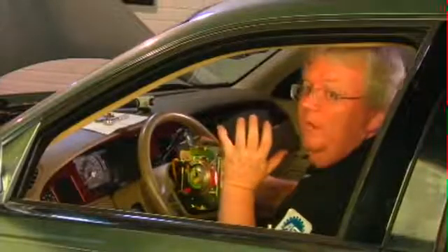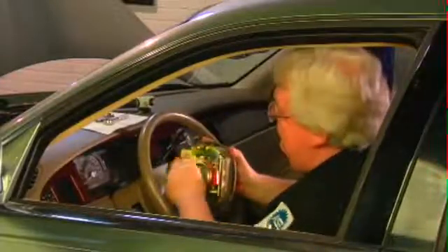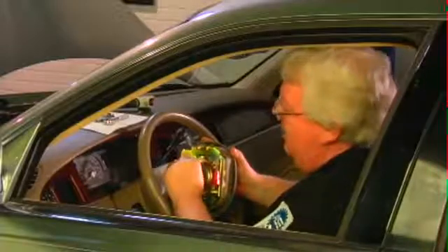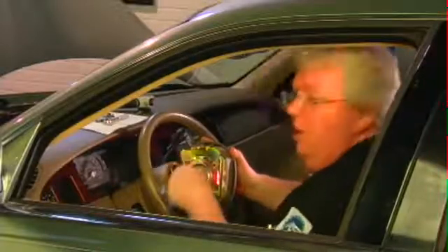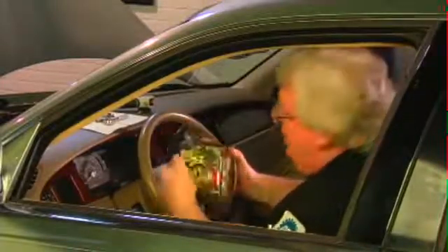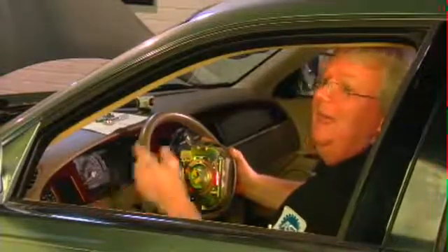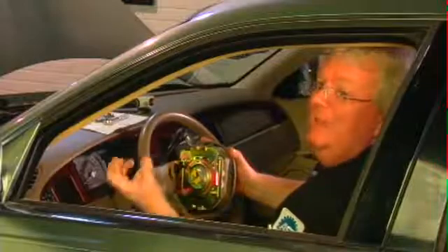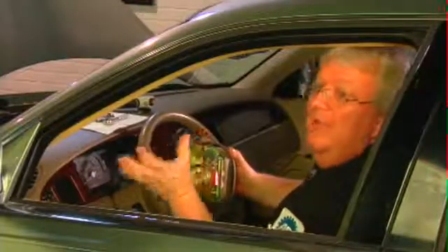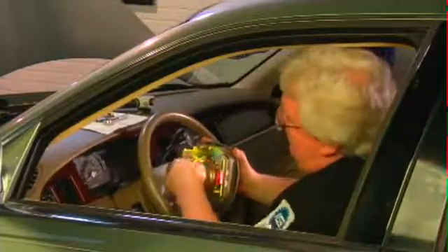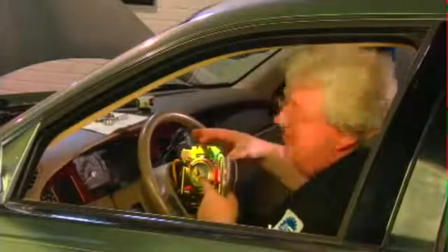Now, since we have disconnected the battery and waited a minute, even if there were shorted wires down lower in the harness getting ready to give power and ground into here, there is no power because the battery is disconnected, and that airbag module itself has the electronic module, its capacitors have drained. But getting these back in the right place is going to be really important.